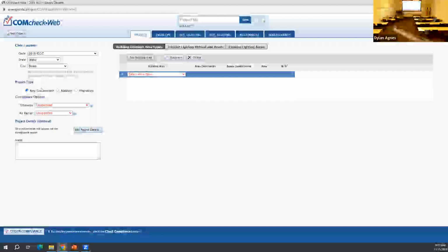Okay, we're in new construction. And then compliance options. These are optional, but this is what I mentioned last time. It's C406. You have to choose one of the options for efficiency if you want. One of those, as I mentioned, is the reduced lighting power. That's something you can do for your interior lighting power calculations. You just click that and it will be applied to the project.